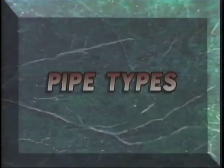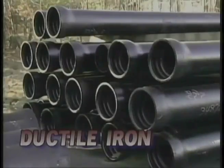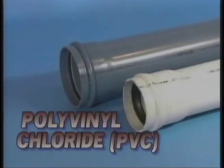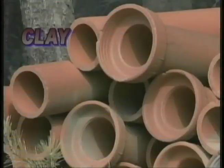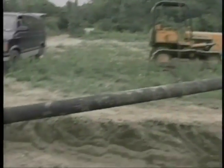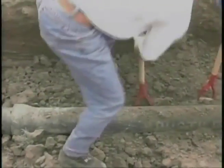Common types of pipe installed from mainline sanitary sewer systems are ductile iron, polyvinyl chloride, and clay. Ductile iron is usually used when the excavation is abnormally deep or when the installation requires a strong pipe that can withstand heavy surface pressure.